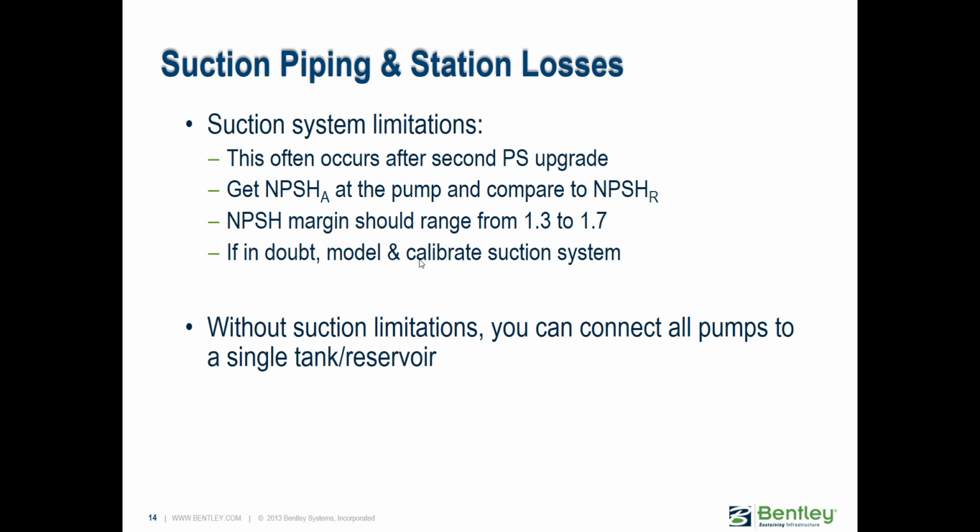So you might have a bottleneck, so to speak, on the suction side of your pump because of that undersized piping. Something you'll definitely want to check in that case is the net positive suction head. As you know, if that drops too low, you can have problems with local cavitation, like the videos that I had mentioned yesterday.